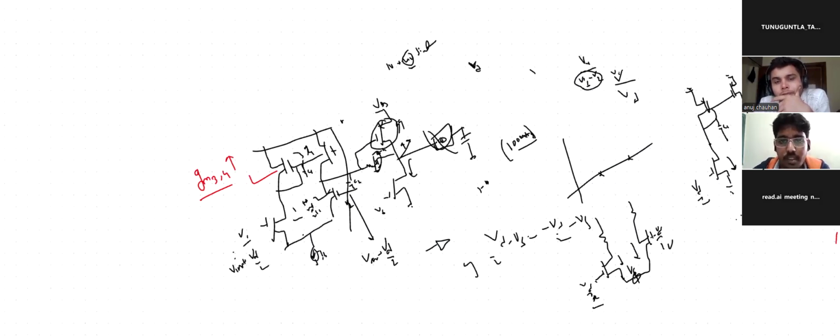Yeah, that is the exact answer I want. You are not saying this from the start: every two signals can be represented. The term representation is important. We can represent any signal in terms of common mode and differential mode. That is what you said, correct. Common mode is V1 plus V2 by 2. Ultimately, this is playing with numbers only.